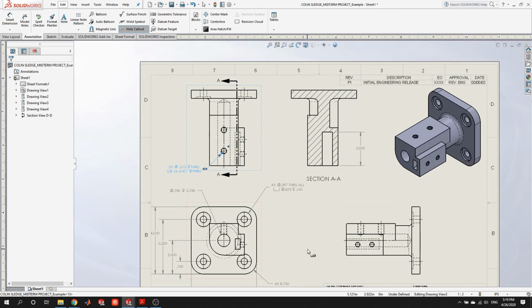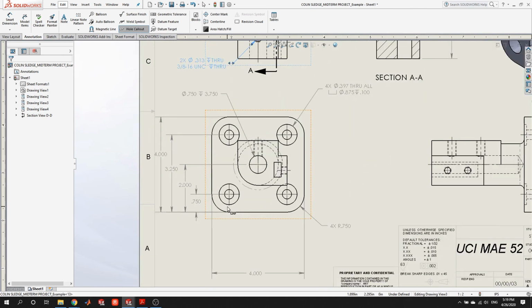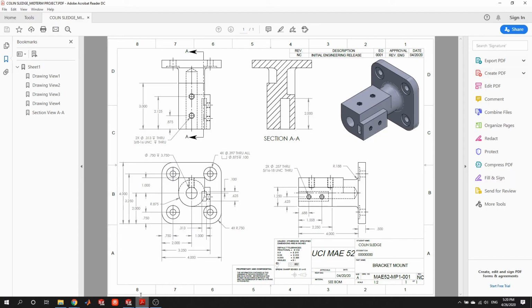The thing you're going to have to be careful about is to make sure that it's clear and that you have all the dimensions. What I recommend doing is printing out this prompt, and when you created your drawing, go through each one of the dimensions and put a little check mark if you have it to make sure that you haven't missed any. Another way to think about it is you could try to envision rebuilding this part and go through each one of these dimensions. And if you don't have enough dimensions to add a feature, it's likely you've forgotten that dimension on your drawing.